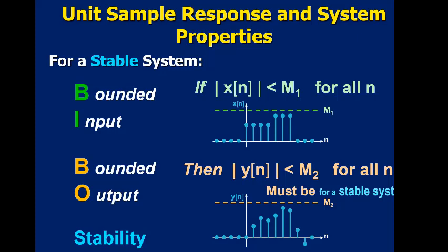It's easier to show that a system is unstable by finding any one input that makes it take off to infinity. As soon as I find one, I rule out that the system is stable. But if I can't find one of those, I can't be sure that the system is BIBO stable until I've tested every possible input. So we need some other criterion.